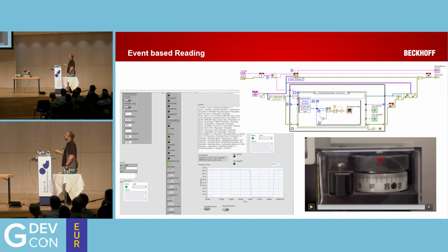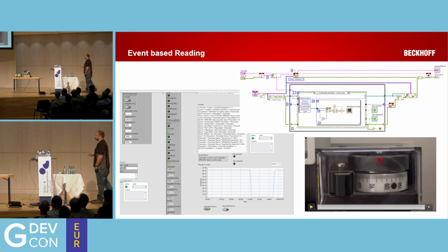So we have demonstrations of this achieving 5, 10, 15 kilohertz cycle rates. We have one customer that's pushing 2,000 long reels, so 64-bit data every millisecond out of a Beckhoff PC via that system, which is actually quite a lot. It's a lot more than they need as well, but they won't reduce it because they like the fact that it sends that much.